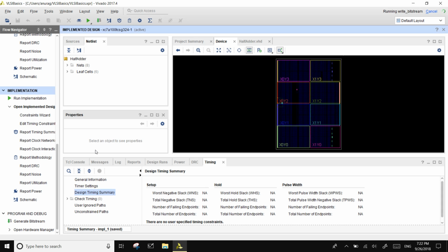Okay. So the programming is very simple. You have a USB port. What it has is a JTAG port to USB. It's a micro USB on the board. You have to just hook it up to the USB of the computer. And once it is hooked up, if you switch it on, it will show you built-in self-test. This is built-in self-test. It's testing all the LEDs and all the switches, so you can see if these switches are working, right?